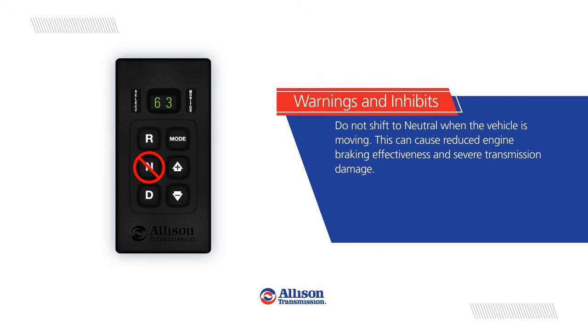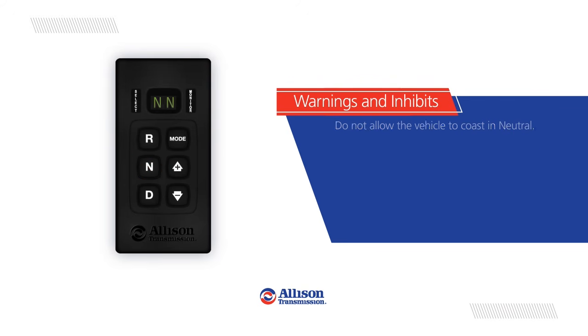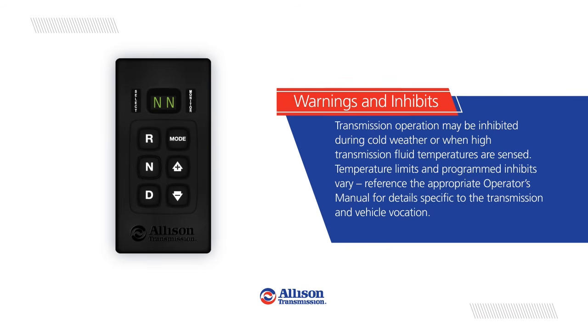This can cause reduced engine braking effectiveness and severe transmission damage. Do not allow the vehicle to coast in neutral. Transmission operation may be inhibited during cold weather or when high transmission fluid temperatures are sensed. Temperature limits and programmed inhibits vary.